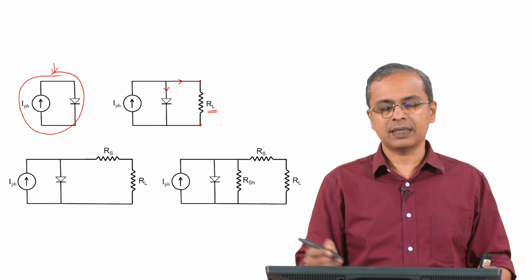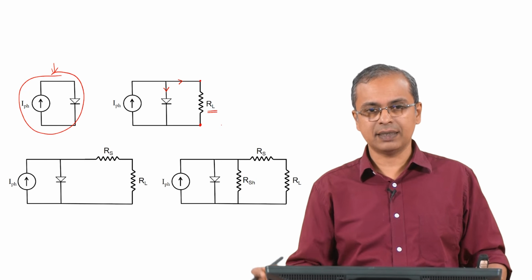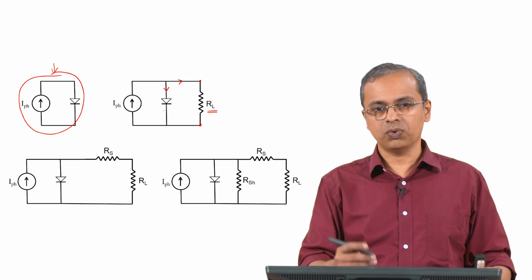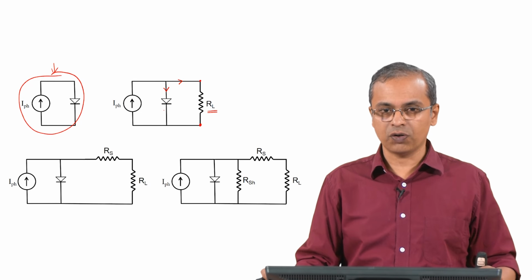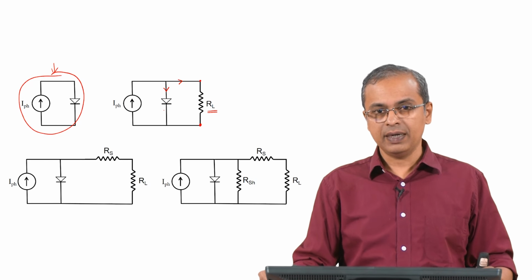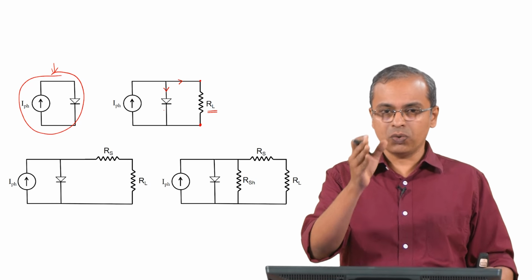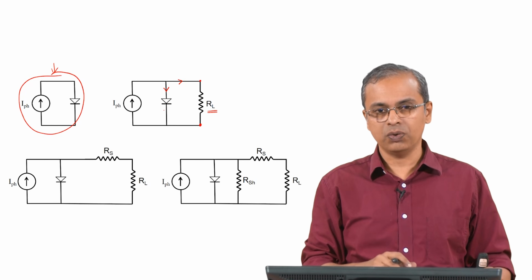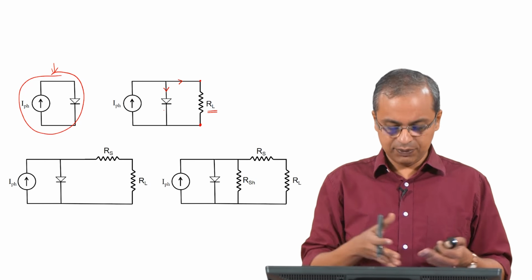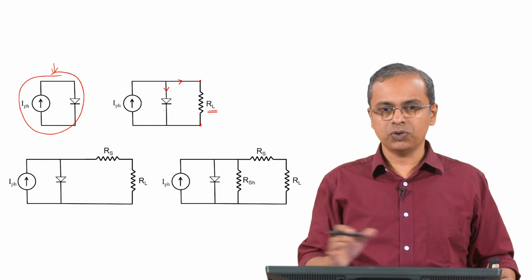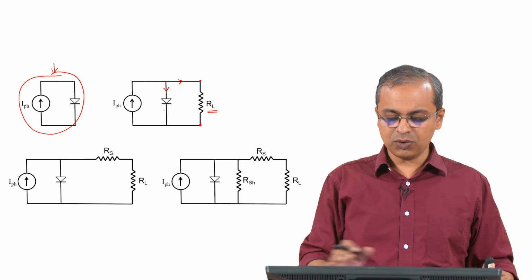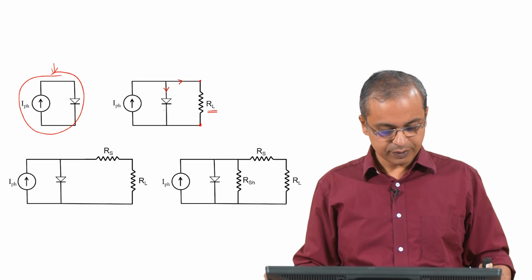You have some electrons going through the external load, which does the job that you want to do, and you have some electrons and holes going through the diode in the forward bias, and they are also lost there. So, ideally you want to minimize what goes through that diode, maximize what goes through your external load. That is basically the idea, but there are some restrictions, which is what this diagram is about, which shows you progressively what are all the different parameters that are involved in this process.